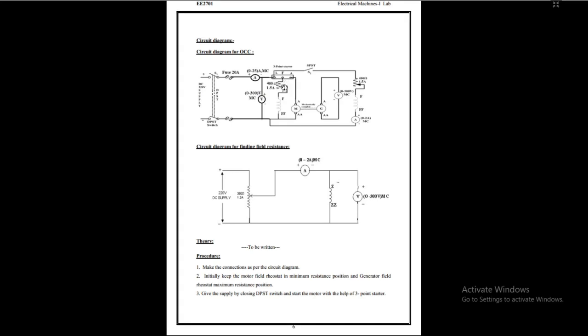The more flux enters, the less speed it rotates with. After that, by varying this field rheostat, we will fix the motor at the rated speed.